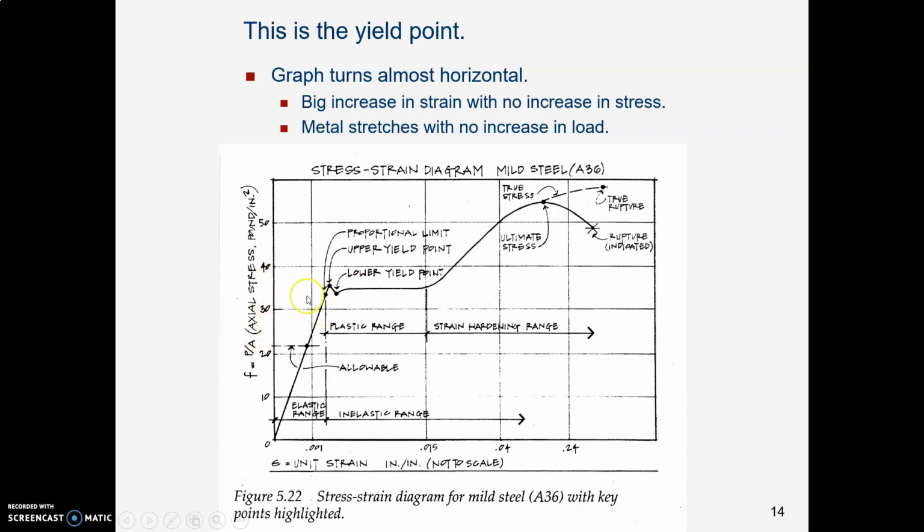Even if you do not increase the load or the stress, you're just, okay, hands off, I'm not touching you. That bar is going to keep on stretching, stretching, stretching. More and more strain. It's in the plastic range.